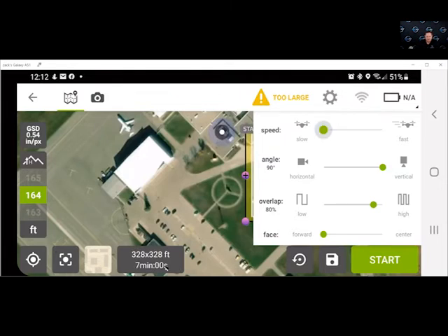And obviously, the slower we go, the longer our flight time. But it also plays a part in the quality of the image that we capture. So as we're flying along, if we have an aircraft with a rolling shutter instead of a mechanical shutter, we might get a little bit of blurriness, things like that, that we need to account for. So we can slow this down if we find that our images are getting blurry, and that will help sharpen them up a little bit. And I believe if you go all the way down, it may even stop to take the individual pictures. But again, that depends on the aircraft and what else you got going on there.